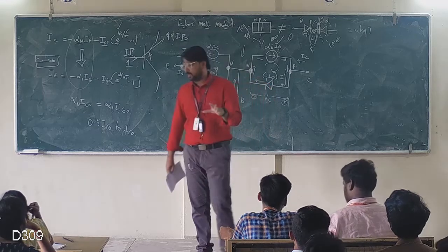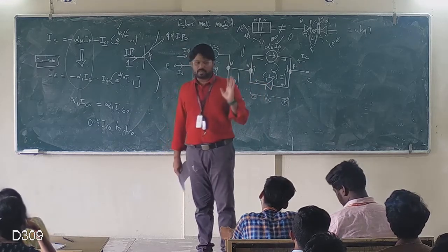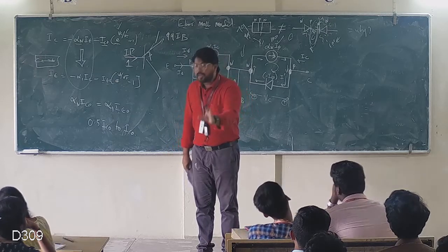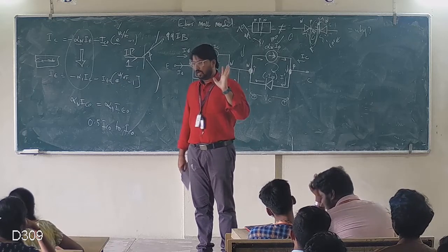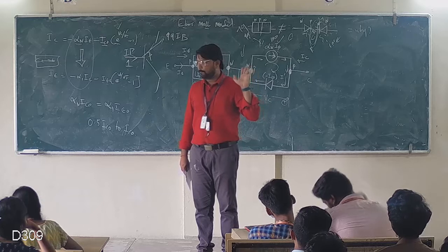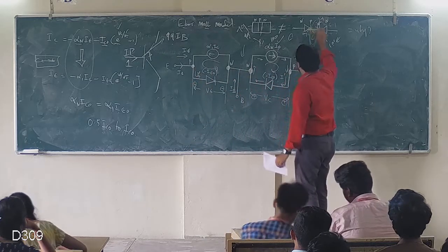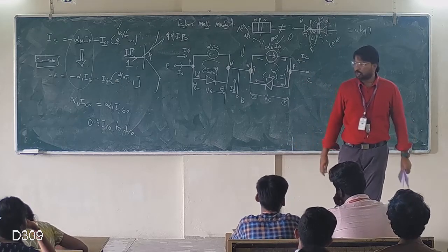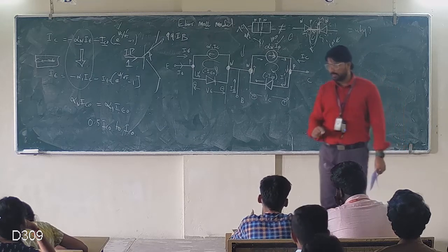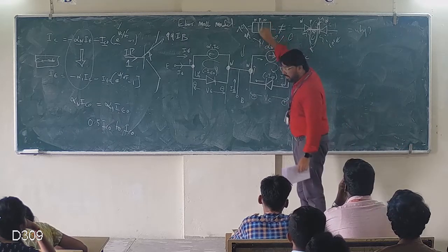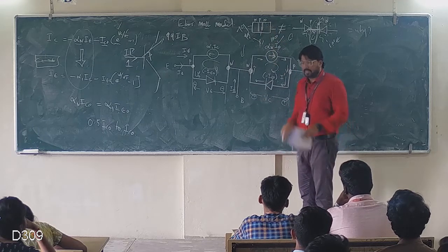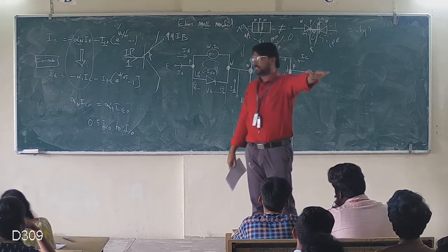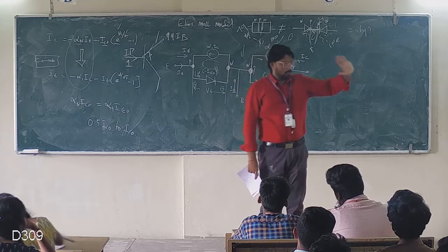Why does a back-to-back connected diode not become a transistor? It fails. Why does it fail to amplify the signal? Because recombination is 100%. No charge will escape from the base, because the base is made up of a conductor. Conductors are rich in charge. Got the point? In a transistor, the base is a lightly doped, thin semiconductor region, so it never takes more than 1% recombination. The remaining 99 will safely reach the collector. Got the point? That is the advantage.